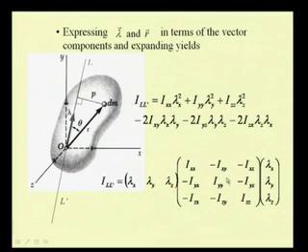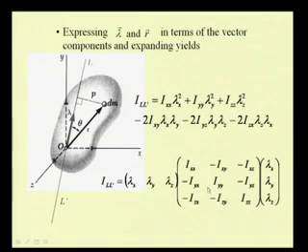So, now this is a more compact form. We know this inertia tensor for a particular axis, then if we know the direction cosine, then we can determine the second moment with respect to any axis passing through the given origin, or the origin of the reference frame for which this inertia tensor has been computed.